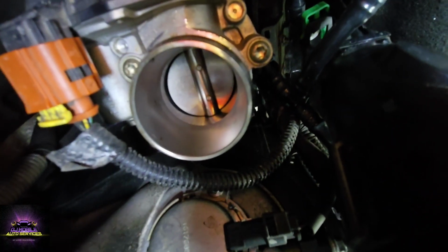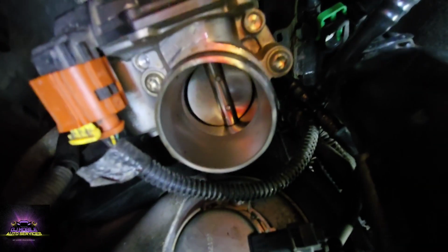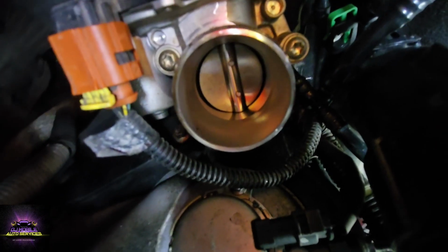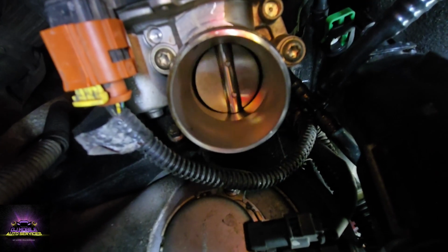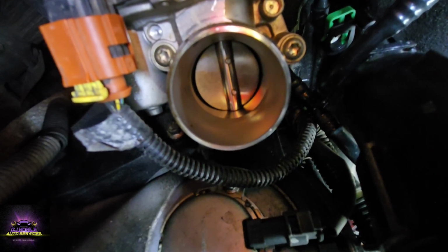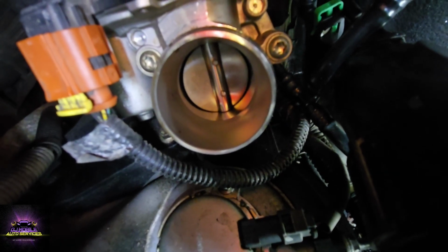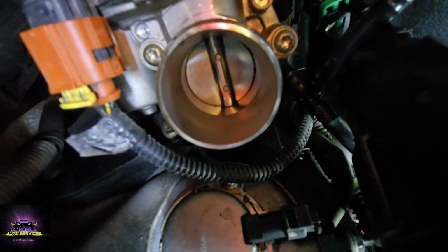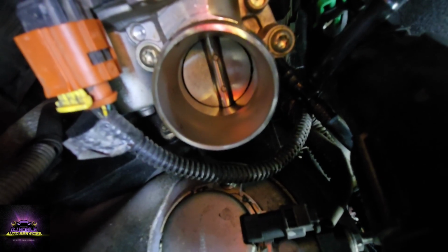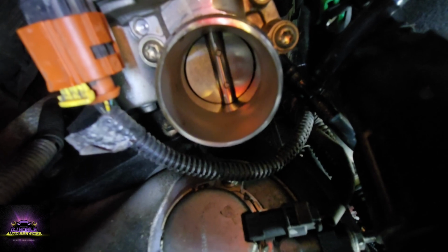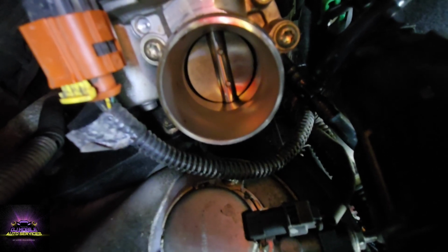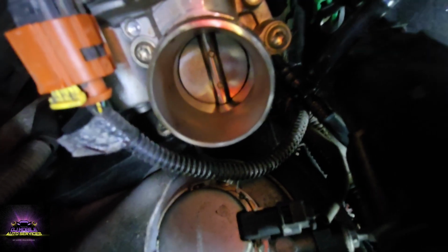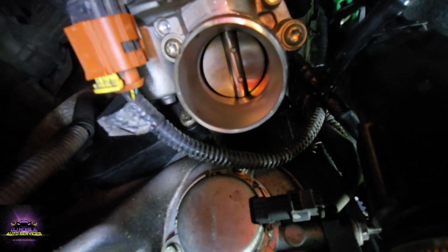Alright, so with key on, engine off, I'm expecting to see the throttle plate move. Right, that's basically just moving out all the debris or ice or whatever sticks around the throttle. So yep, with key on, engine off, I'm seeing some movement on that throttle plate. So let's see if we can start the vehicle up. Let me ask him to step on the accelerator. So it does open a little bit, but not much because you're not getting any response, right? So let's hook up our tools and let's see what's going on.